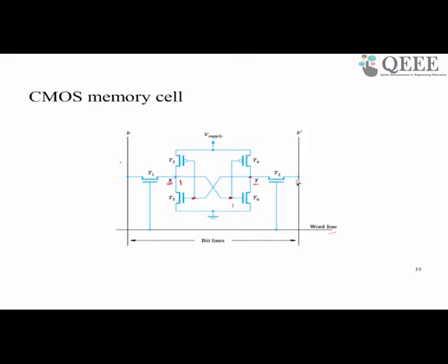But it will be difficult for these signals to drive the external sensing circuit. To enable that, we pre-charge these two lines. By pre-charging, we mean bringing them to a value halfway between 1 and 0.